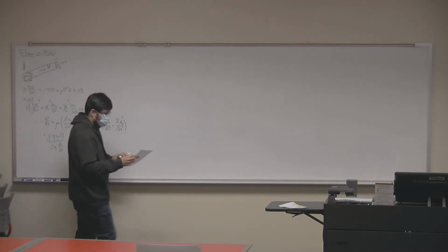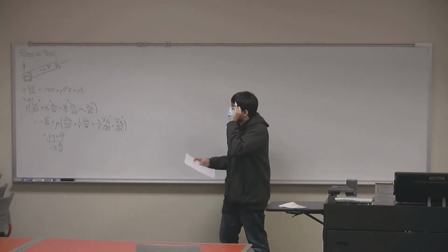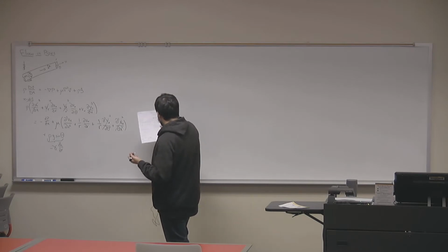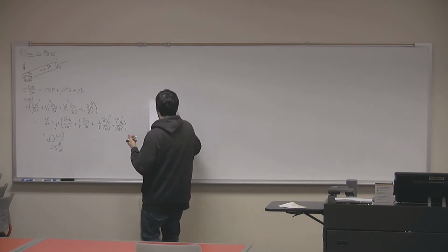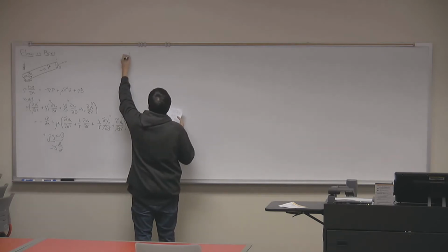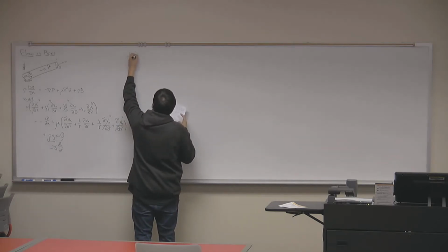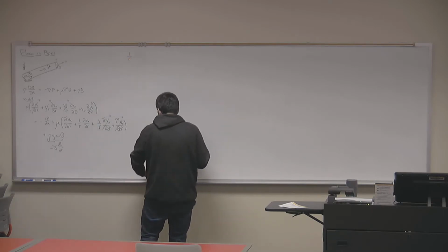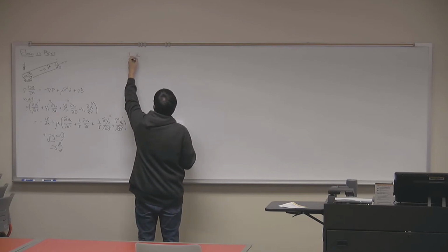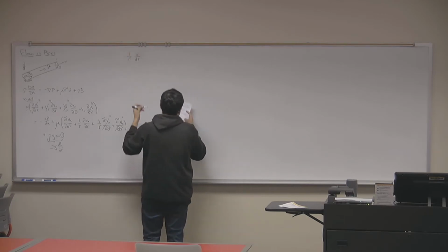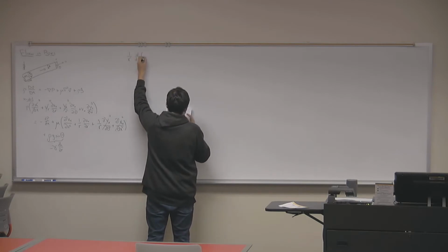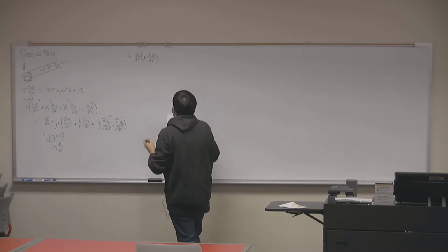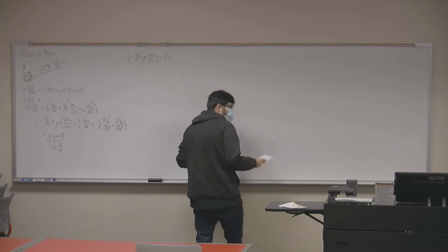And after solving this equation, again, the solution is in the video I uploaded. I just wanted to make sure we know where these terms are coming from. But after solving this equation, in class, we ended up with the following equation: 1 over r times the derivative with respect to r. Even though we're writing partial, these are actually total derivatives because velocity only changes with respect to r in this case. So the derivative with respect to r of r times the derivative of the velocity with respect to r, and all this was equal to a constant lambda.